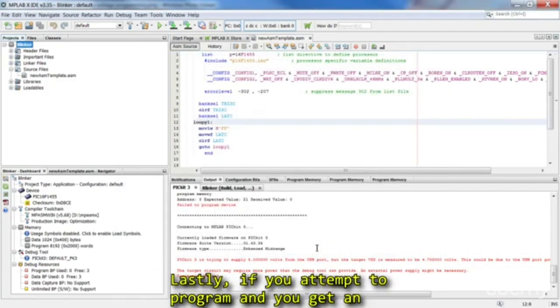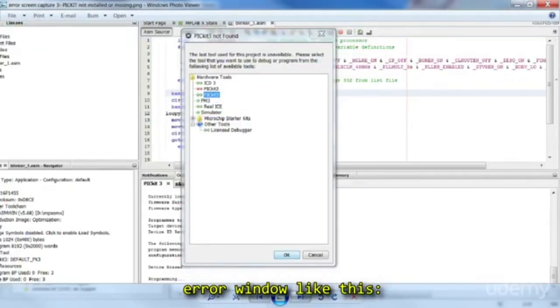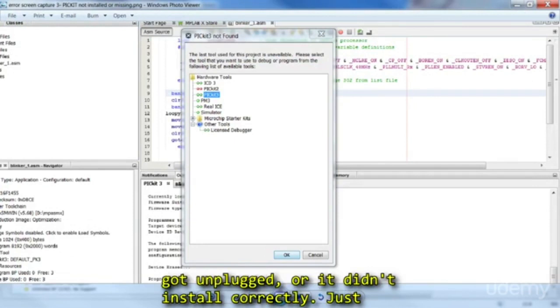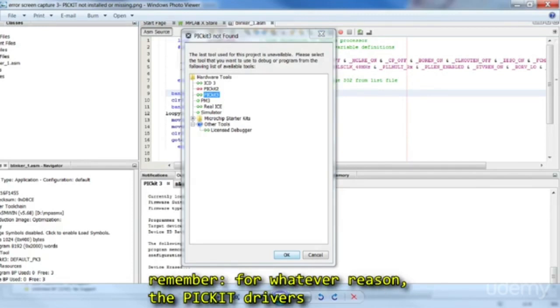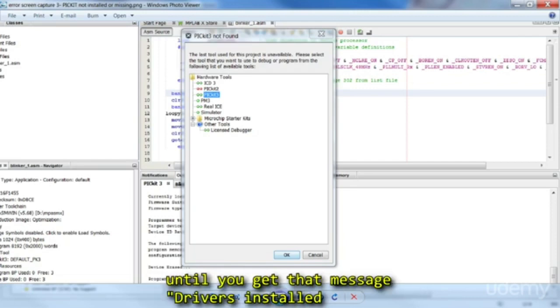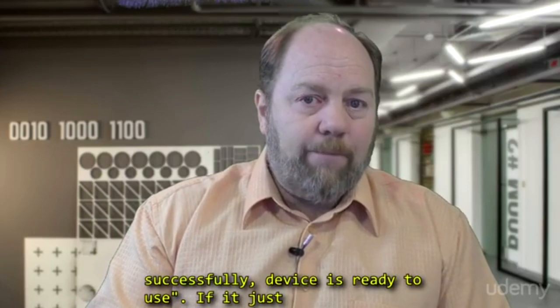Lastly, if you attempt to program and you get an error window like this, it means either your Pickit isn't plugged in, or it got unplugged, or it didn't install correctly. Just remember, for whatever reason, the Pickit drivers on Windows machines took forever to install. Wait until you get the message, drivers installed successfully, device is ready for use.